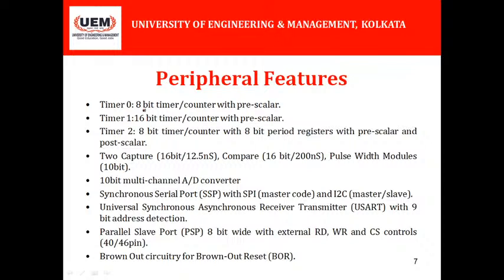That means we have to scale timer 0 and timer 1 down before the operation, and timer 2 can use either prescaler or postscaler. That means before the operation and after the operation we can scale this device.